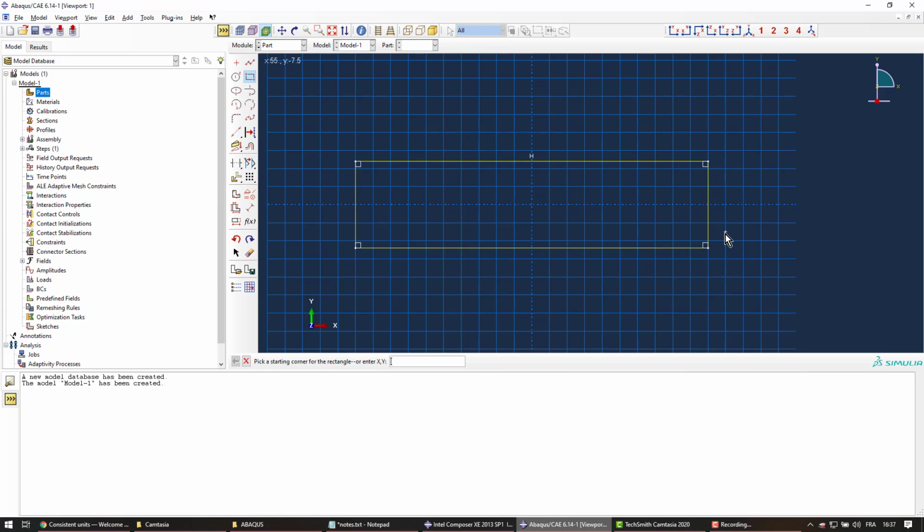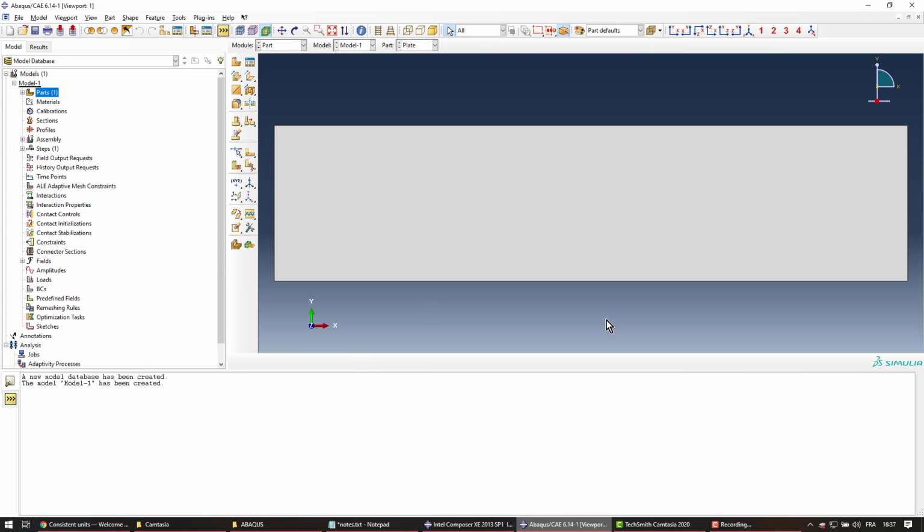If you click down the wheel, it basically means accept or confirm next. So while I'm here, if I click the middle mouse button, or button 3, then it accepts. Then I just moved out of the tool. And then if I click the mouse button again, it would be equivalent to clicking done here. So I'm going to click button 3, and I get my part.